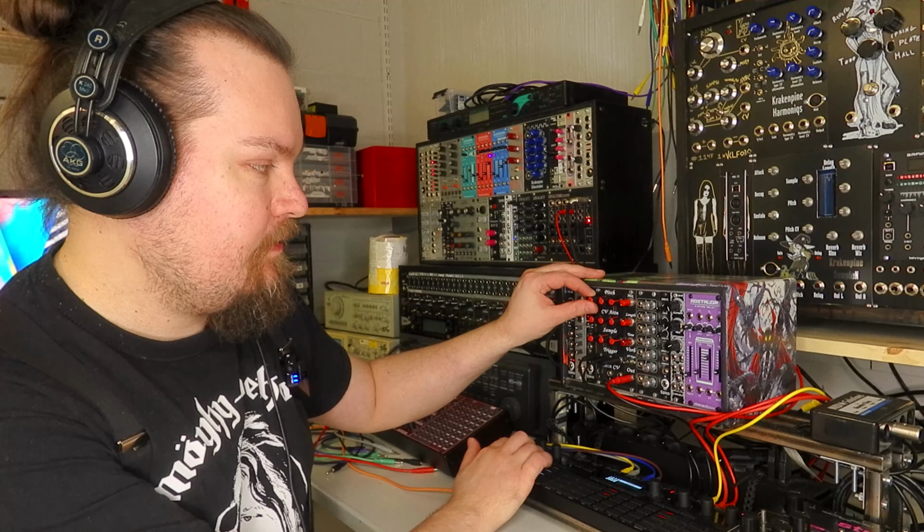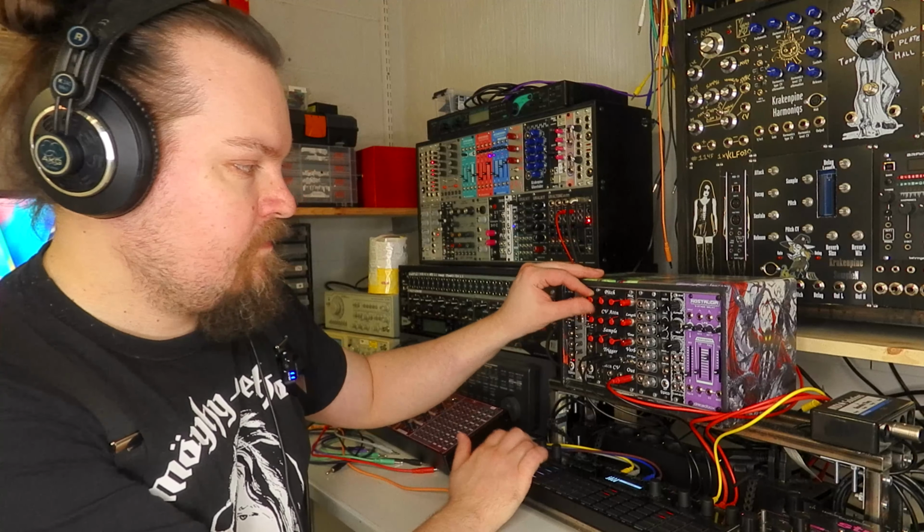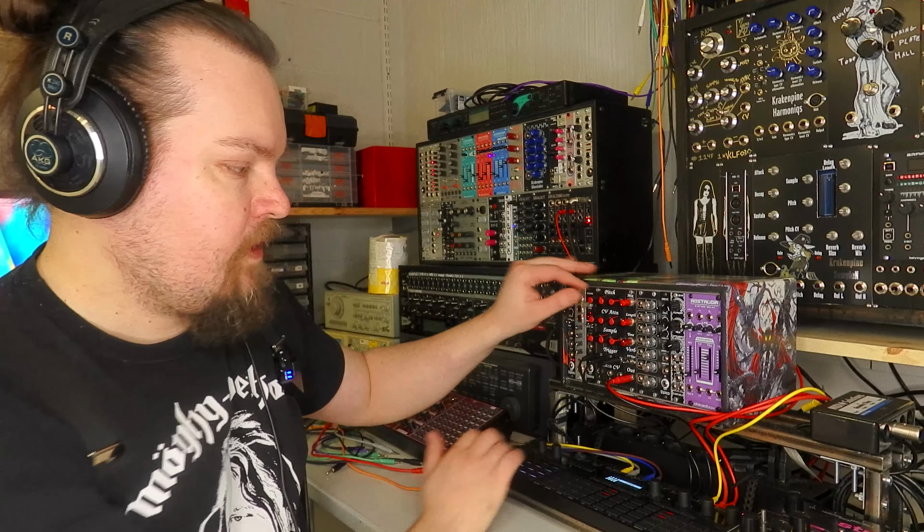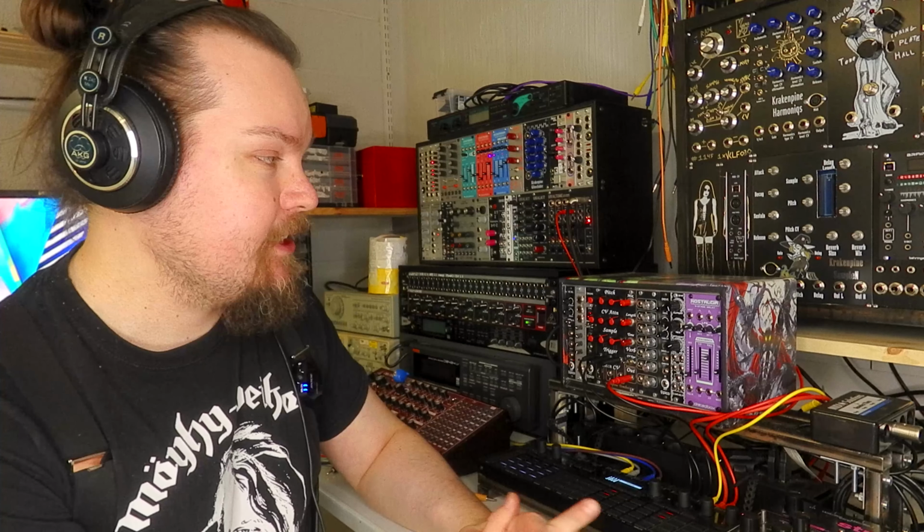one for pitch. The pitch goes from -2 octaves to +2 octaves, or a quarter of the speed to 4 times the speed. And there's also a control voltage in for the pitch, and a potentiometer to attenuate the CV signal, so you can have slighter variations.